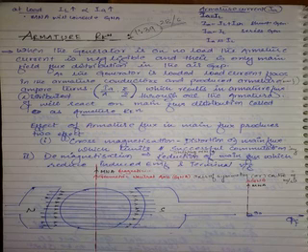Actually, the flux lines are concentric circles. Like this. So we are interested in what is happening inside, right? This particular part. So now we will give a direction. Similarly, when it comes to the conductors lying under the South Pole, what is the direction of rotation of flux? Anti-clockwise. It's coming outside. So the thumb indicates the current. So now it is anti-clockwise.